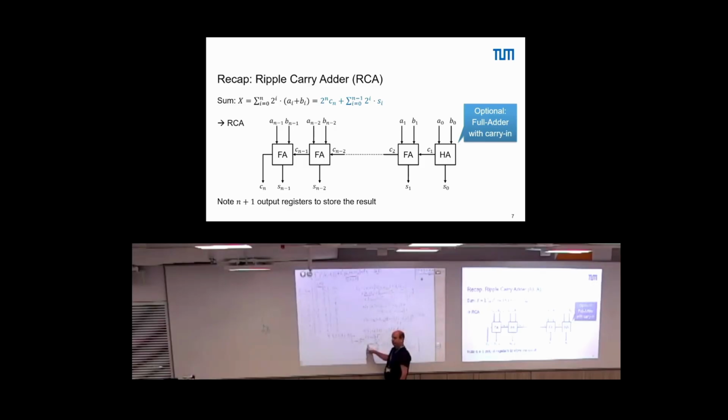This AND here blocks, so only the upper part counts, so we have here an AND of AI and BI. The OR gate just propagates the signal, so we are back at the half adder, right? So if we put the C minus 1 signal to 0, we have a half adder, just as we wanted for addition.